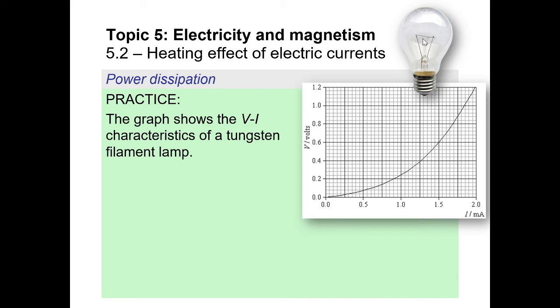Now, when the electricity flows through the tungsten filament, it starts to heat up. As the electrons encounter that resistance, it starts to release energy in other forms. So it converts the electrical energy going through the wires into light energy, and unfortunately, thermal energy. Most of you should probably know at this point that these bulbs are really inefficient. Of 100% of the electricity that goes into powering them, 90% goes into producing heat, and only 10% goes to producing light. The compact fluorescents are much more efficient than that, which is why they are preferred.